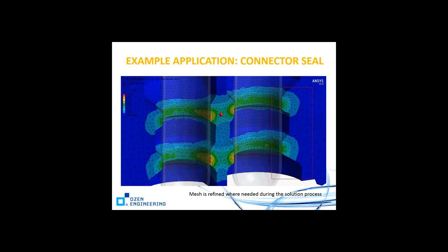Yes. But you can do that in 14 by just setting the material property to hyperelastic, like a Mooney-Rivlin model, and then allow it to do that. It doesn't remesh from what I've seen. In version 14, it doesn't remesh. So if you were trying to solve this in 14, it will probably stop.